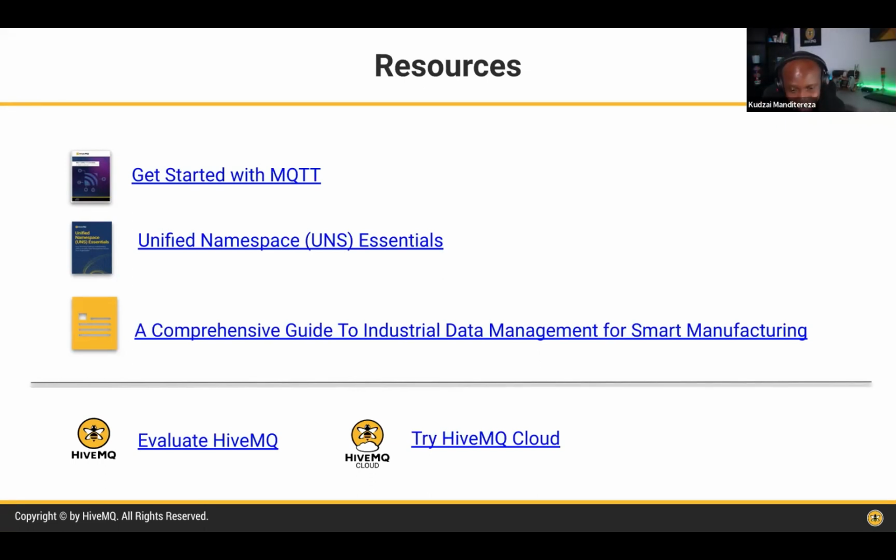Good question. It really depends. In most cases, you could be using an IIoT platform. For example, there are tools like Ignition, which is a SCADA system, and HiveMQ, which is a DataOps system. You've got ThingWorx. There are different platforms you could use to perform that contextualization at the edge or within your enterprise before you push it into your MQTT broker, that central hub of information. So it depends, and Node-RED is also very much usable.